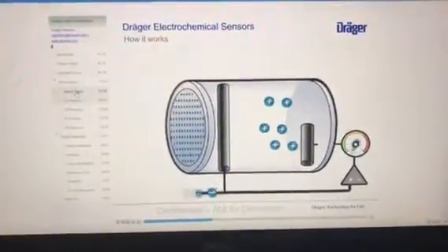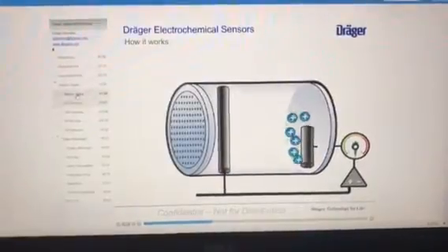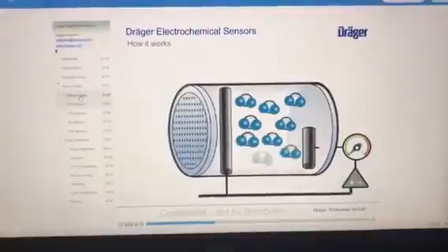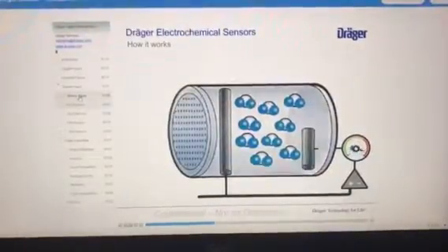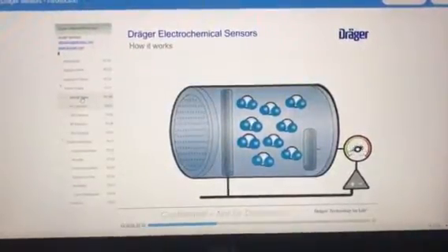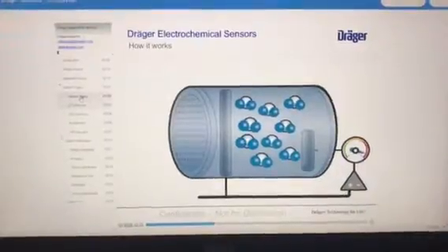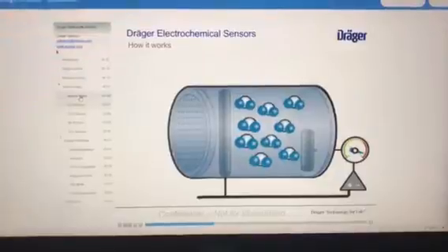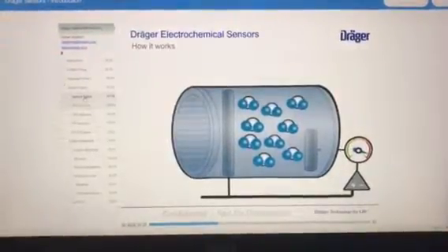A dual electrode sensor does, however, have many drawbacks. For instance, if high concentrations of gas occur, this leads to higher currents in the sensor. This high current can lead to unusable readings, or in the worst case, it can cause the chemical reaction inside the sensor to stop during the measurement process.